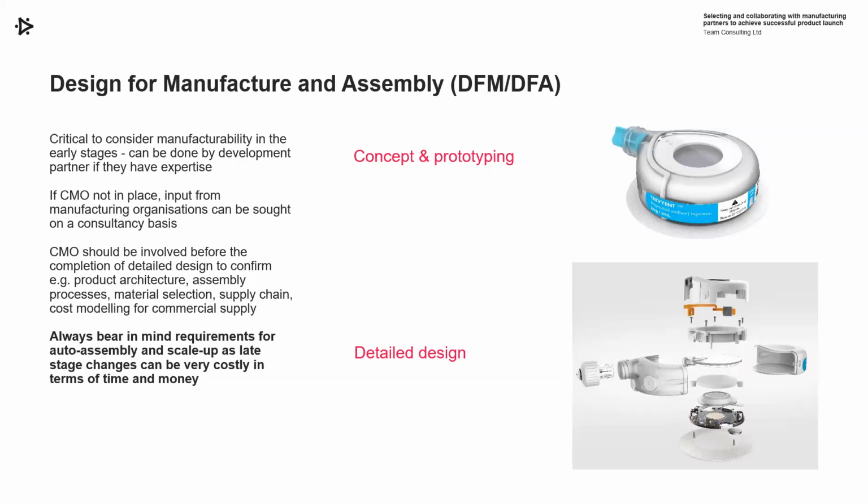And as I've said before, if the CMO isn't in place, you can maybe get that input if needed from other sources. You do need the CMO to be involved before completion of detailed design, really thinking about product architecture, assembly processes, material selections. They may have certain preferences there, supply chain, etc. Making sure you've got a good, accurate cost model for commercial supply of the product. So definitely wanting the CMO in place to contribute to these DFM, DFA activities during the later stage of detailed design.